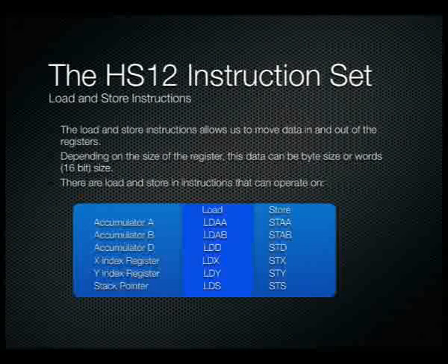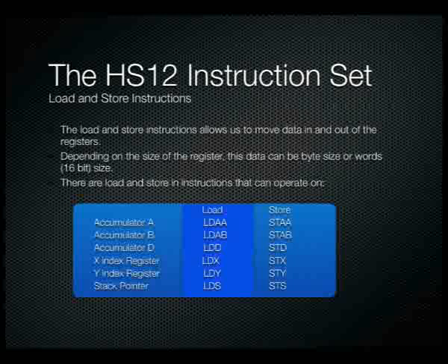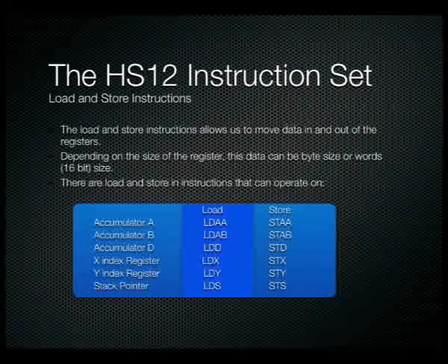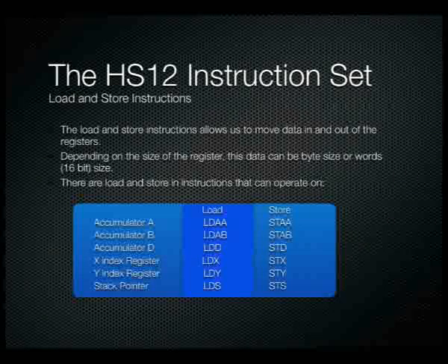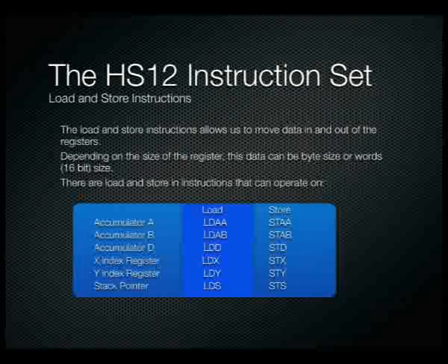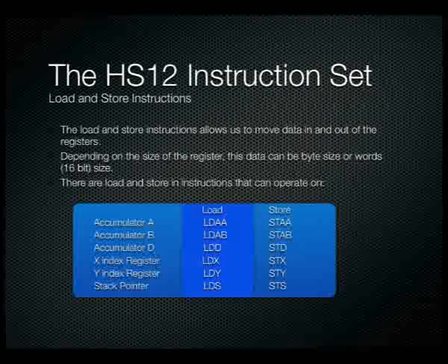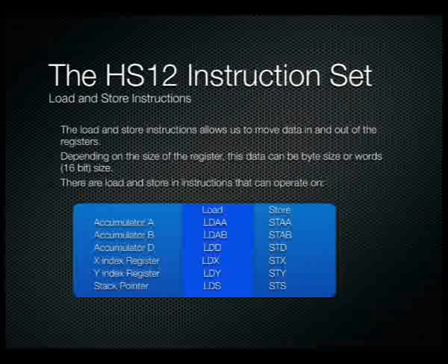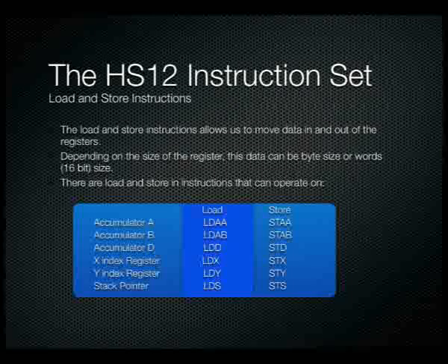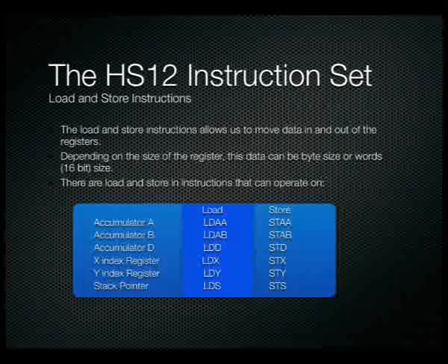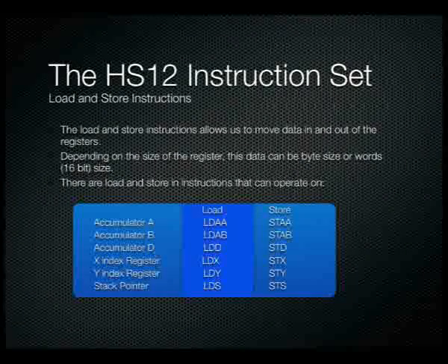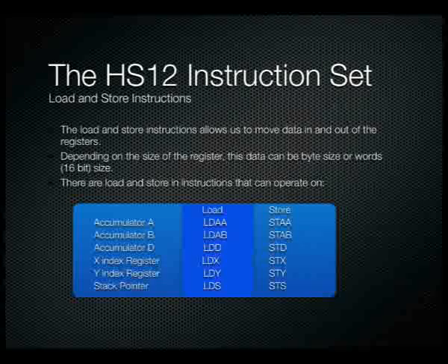The first category we really want to talk about is of course the load and store instructions. Load and store instructions allow us to move data in and out of the registers inside our processor. We can use a load instruction to load values out of memory into the core, and store instructions to move them back out of the core into memory. Depending on the size of the register that we're moving the data in and out of, the operand or the data that we're operating on will be dependent on the size of the register. If we're using an 8-bit register, then the data that we're moving around will be 8 bits. If it's a 16-bit register, then the data that we're moving will be 16 bits.